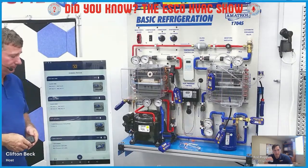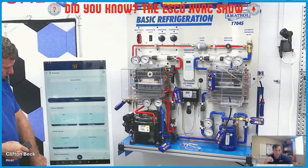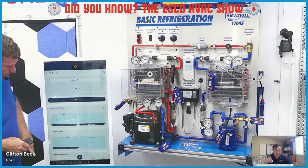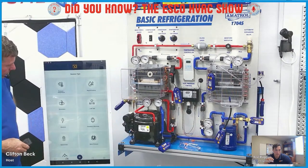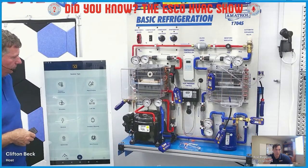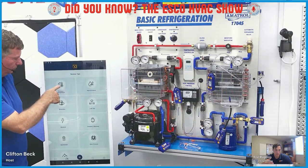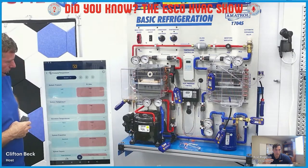So the second hotkey on the bottom, the second one in from the left, is your sessions. I'm going to have you hit it again to go back to the main session screen. So this allows you to pick what session type we're working on, right? So the upper left one is pressures and temperatures. So to look at your refrigeration stuff, let's go there. And right now it's blank because we have no connected sensors.